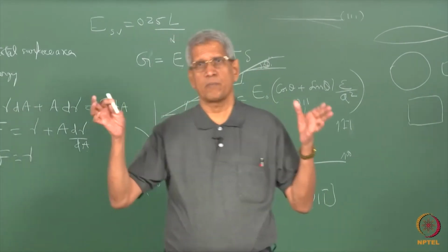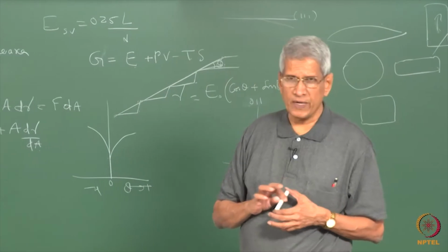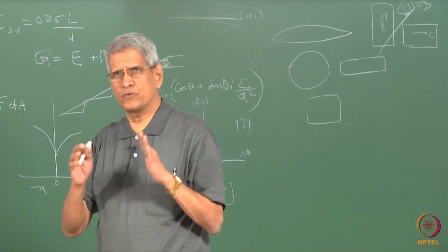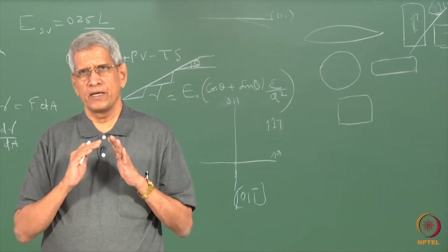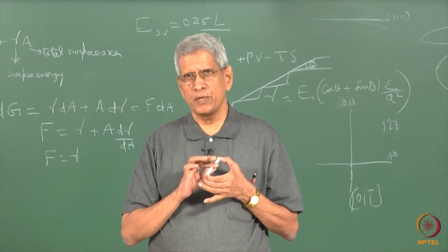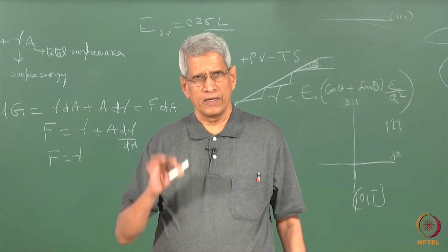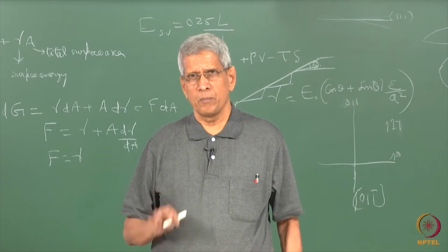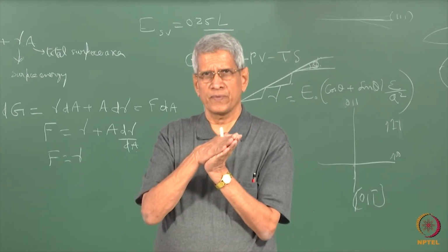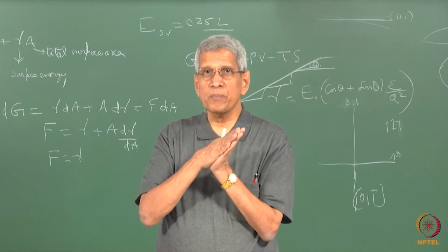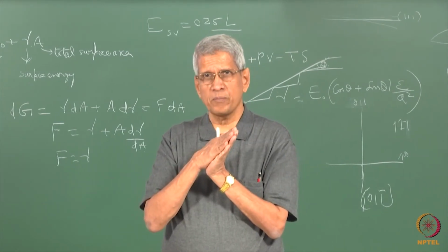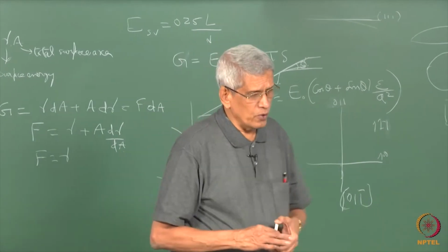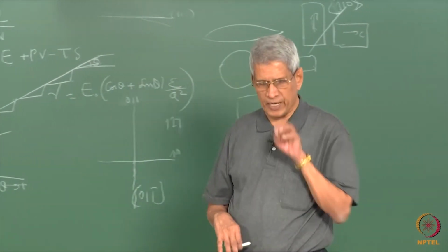These are the CSL type of boundaries, which we will come to later. A twin boundary is one simple example. If we take FCC twins from one to the other, the misorientation between the unit cells is very high, close to 50 degrees or of that order. But the boundary where they meet is on a one-one-one plane, an undistorted plane, with perfect matching. So the energy of that boundary is going to be extremely low. These are the types of special boundaries we can have.